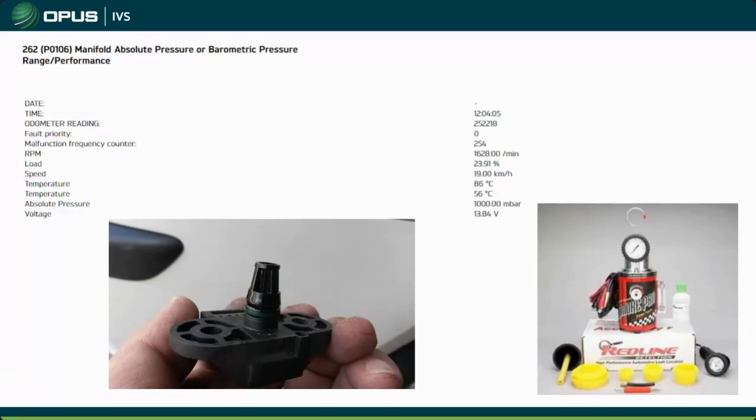So even though the part looks good and it fits well and everything, you'll put this part on and you'll end up with the same fault or new faults. And it's like, what the heck? I put a new one on. My recommendation for these kinds of components is to get factory dealer supplied parts. And I know that's not always possible, but there are some things, especially like that valve under the 3-liter supercharger. The price difference usually isn't so much that it's worth having to do the job a second time. So better off to tell your customers, look, I'd rather put this factory part in. It's kind of buried. We don't want to risk an aftermarket part.